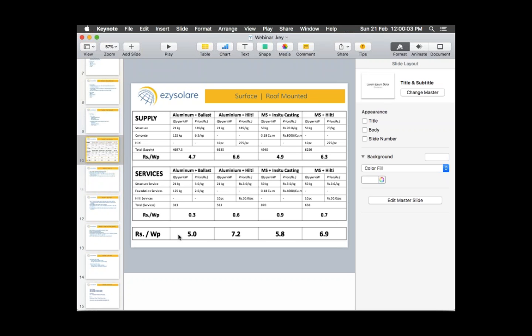Have you had any practical example doing that? Yes, in Punjab, we have a running project we can even share with our attendees. We can find out the generation numbers, how it has been performing, the incremental generation it is giving. What the vendors were claiming, it is giving at least 1.5% more. So your recommendation will be to do a polar 1.5 axis structure. Yes, and that too depending on the latitude and longitude, because we should invest very carefully in the structure and compare returns with it. With double axis, yes, you can go with it, but I don't think it will be worth the money at the prices we are getting today.